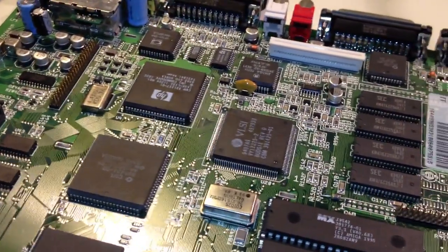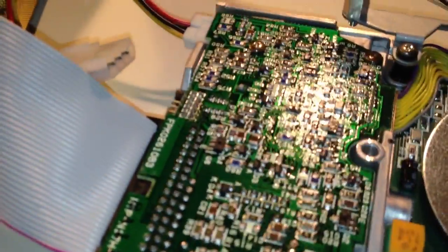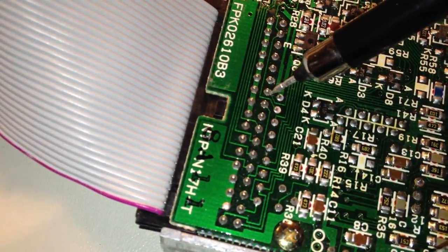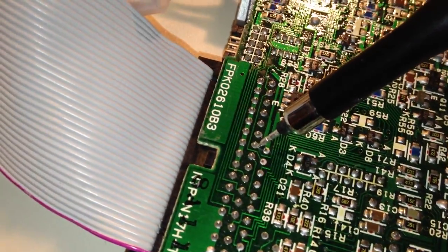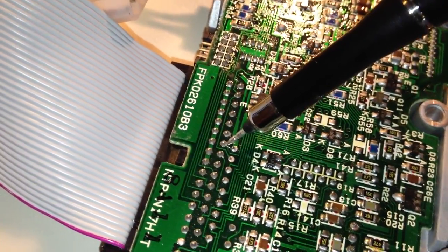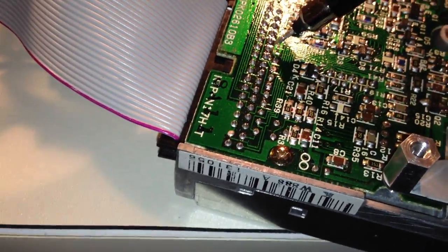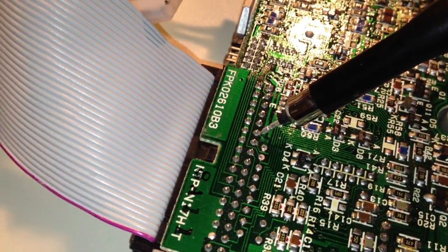Okay, so here I am with my Amiga 1200 motherboard, which is in fully working condition, and I have it hooked up to an internal disk drive here, which I have flipped upside down, as you can see. Now, as I mentioned, there are two signals we're interested in, and one of them would be this one, right on pin 22. And there we have the incoming serial data to the floppy disk drive. So when the disk drive is performing a write operation, a lot of serial data is coming into this pin here. And the other signal we're interested in is this one on pin 24, and that is the gate signal.